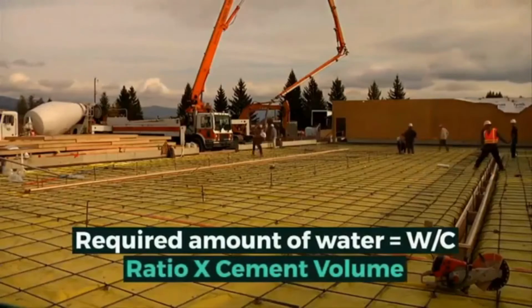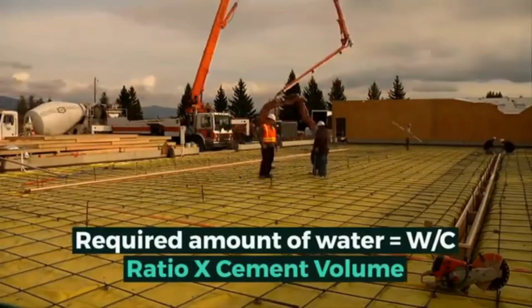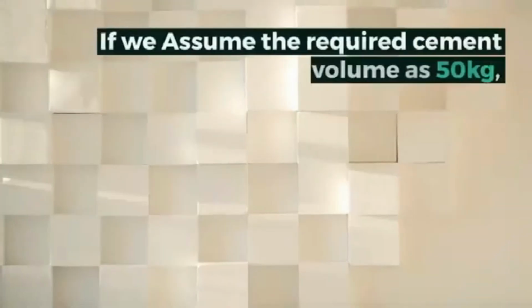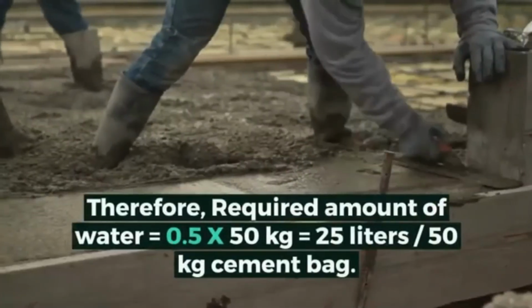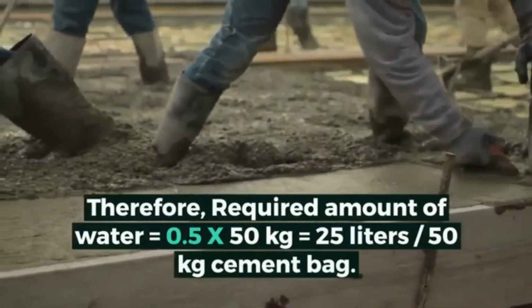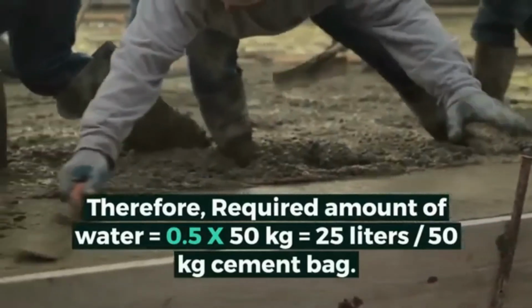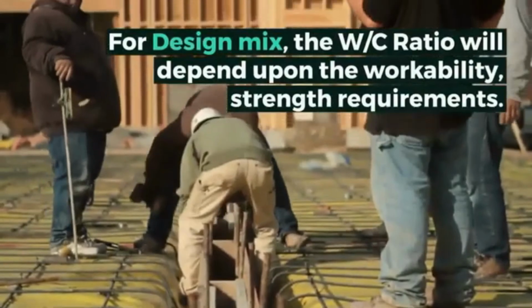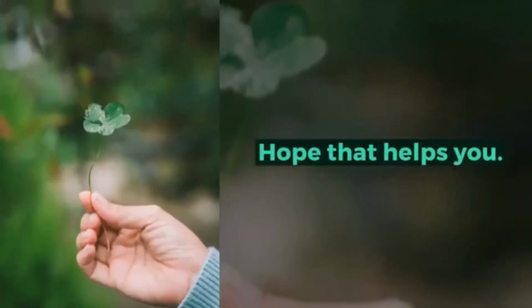The formula to calculate the water quantity for concrete is: required amount of water equals water-cement ratio multiplied by cement volume. For example, if we assume the required cement volume is 50 kilograms, and water-cement ratio is 0.5, then the quantity of water will be 0.5 times 50 kilograms equals 25 liters per 50 kilogram cement bag. For design mix, the water-cement ratio will depend upon the workability and strength requirements. Hope that helps you.